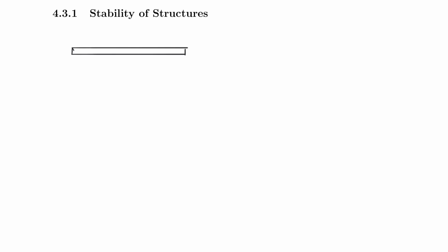And you have done this in the past already when we talked about simply supported beams and cantilever beams. So let me take the example of the simply supported beam. If I would just show this here, I would have a support block here, and then maybe a support block here. And the layman would say, hey, the system is already stable, it's not going anywhere, but the engineer knows better that this system is not stable, although the system cannot fall down, and let's pretend it also cannot move up here, because it's anchored to the ground through these blocks. And although the system cannot rotate anymore, this system is technically free to move left and right.